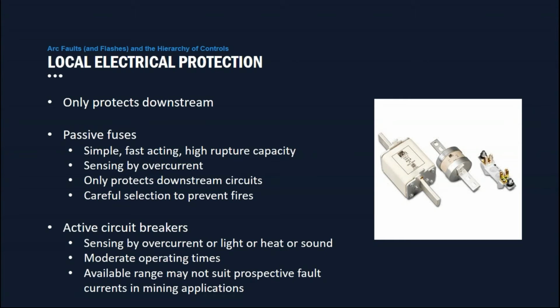We need to be a little bit careful with using fuses. There are a number of instances where fuses have been put in to protect electrical equipment but end up in a fire, where we have a high impedance fault, which sits there drawing current through the high impedance fuse, because it goes into a semi-high impedance state. Then we have current flowing through high impedance. It gets hot, it catches fire, and the hazard there is the fire rather than the electrical fault. So we need to be a little bit careful in using passive fuses in these applications.